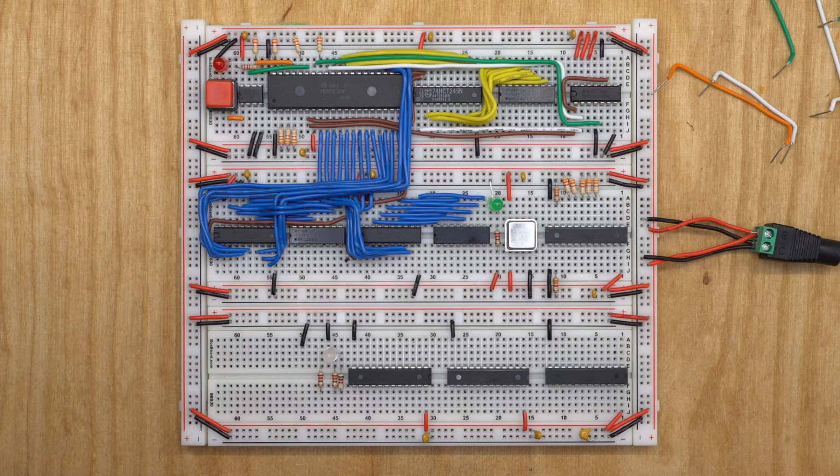On the first slice, we have the reset circuit, the CPU, the bidirectional data buffer with its damping resistor pack, and I replaced the old octal control line buffer with a 74HCT125, which is a quad buffer with individual output enables. On the second slice, we have the 2 address bus buffers, each with their own damping resistor packs.